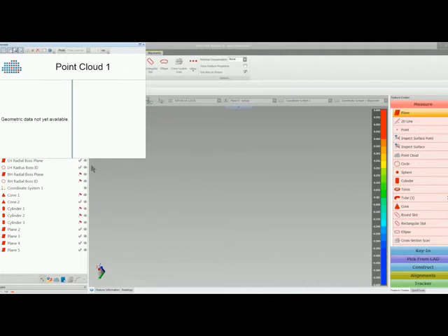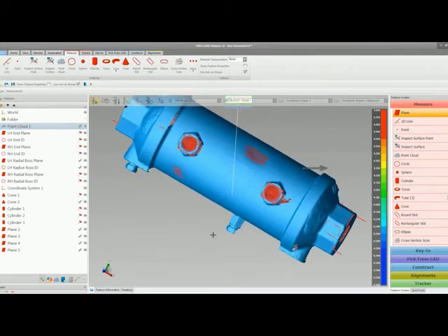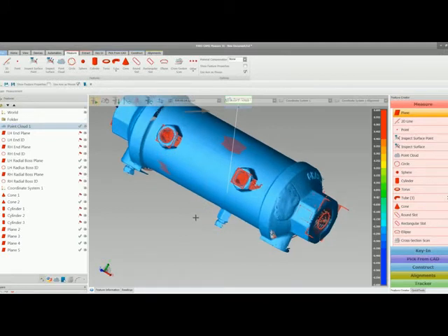So you can see that very quickly I'm capturing loads of points on the surface of this part. Basically 2,000 points 280 times a second. One of the things that I did was I measured a plane on the surface of the table and used that as a clipping plane so that it didn't capture any data physically on the table, which saves you a lot of time afterwards where you've got lots of extraneous data, you need to go in and delete that data out.